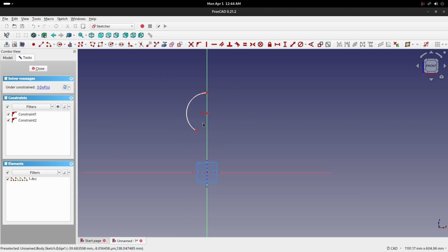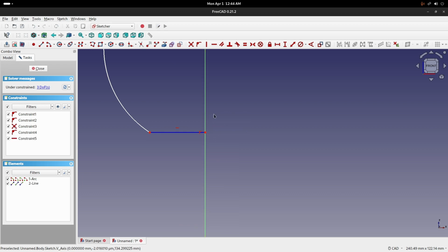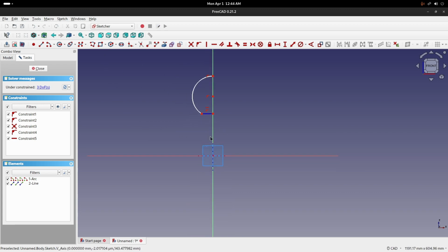Okay. Now what we'll take is a construction line. If you click on toggle construction geometry, you will get a construction line. So what does this do? This line doesn't actually get to be a part of your actual sketch. It's just used so that it can guide you through the drawing. I'll click on this so that it's fixated. See this line? It shows that it's vertical. From here on, we can make our other lines so that we can create the body of the chess piece.